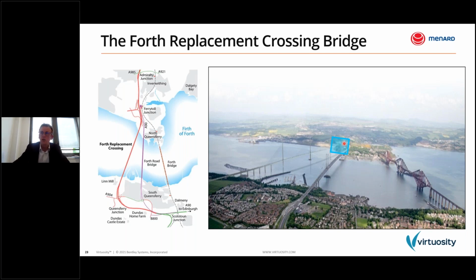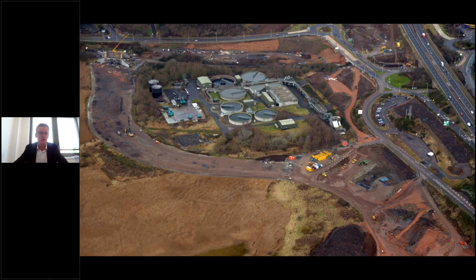And you can see here, this is a working platform done for ground improvement works. You can see here this is a CMC rig. So the first part of the road here was designed with PLAXIS 2D. It was, I would say, quite a usual cross section. It's a symmetrical embankment over soft soil, so nothing very particular. So we used PLAXIS 2D.